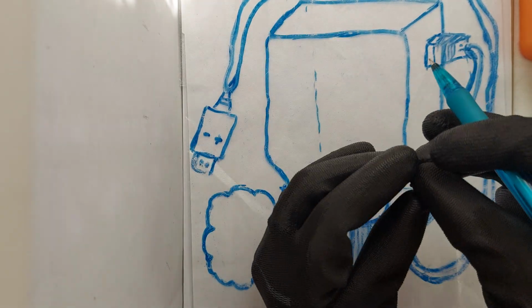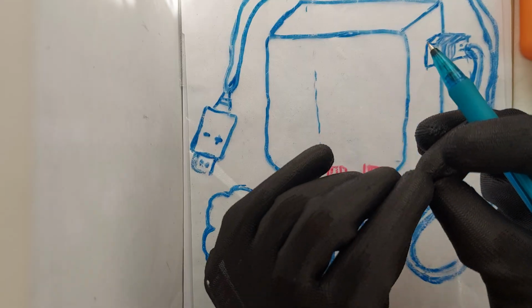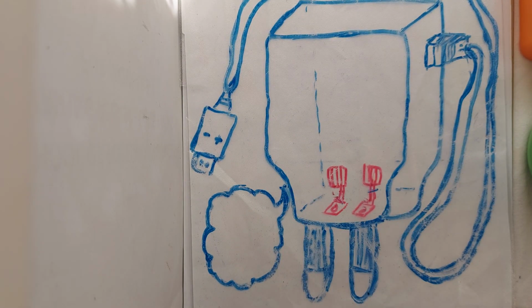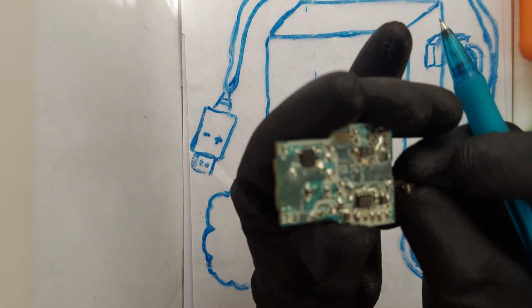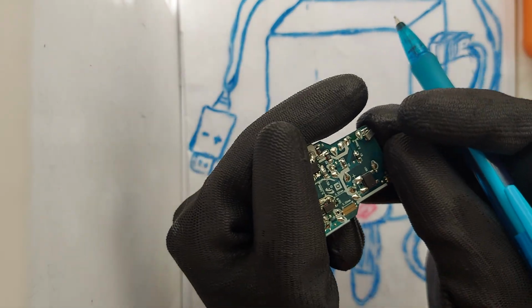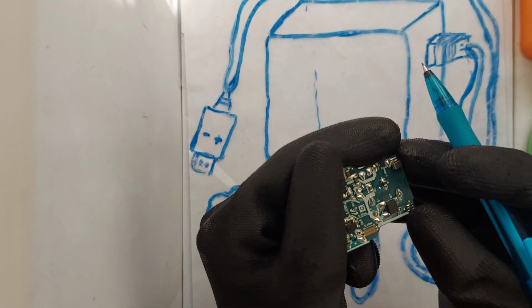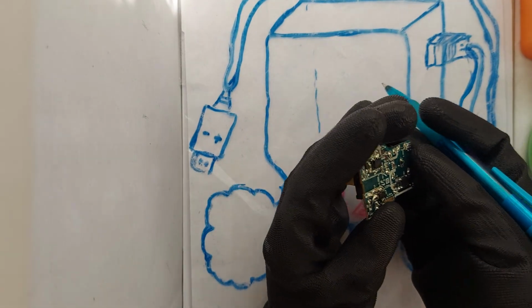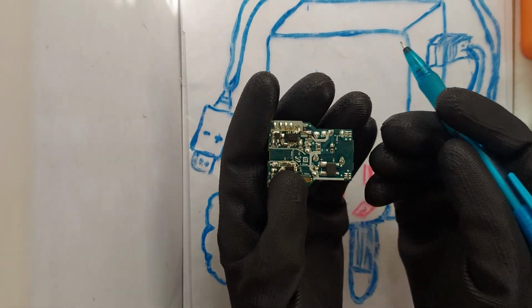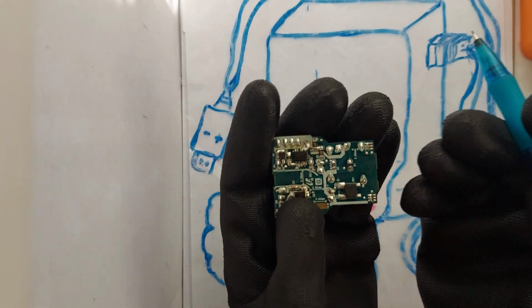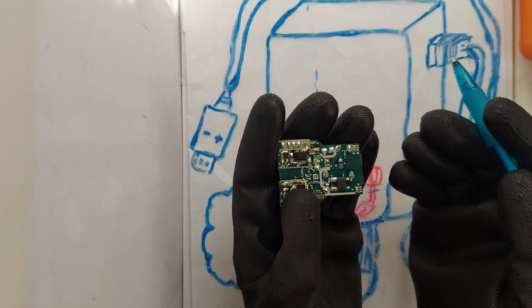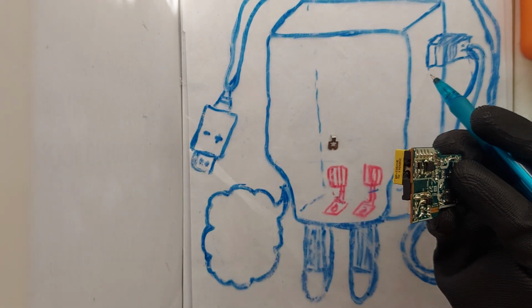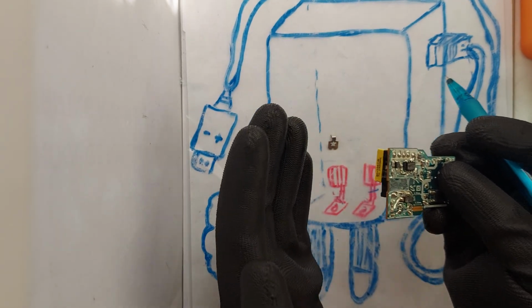So the strips, as you can see here, are directly soldered to the PCB surface. And I will show to you right here, as you can see. No holes, as it is an SMD board. The pins and the strips transfer 100 or 240 volt AC electricity to the circuit, which is then converted to the 5 volt DC for charging.